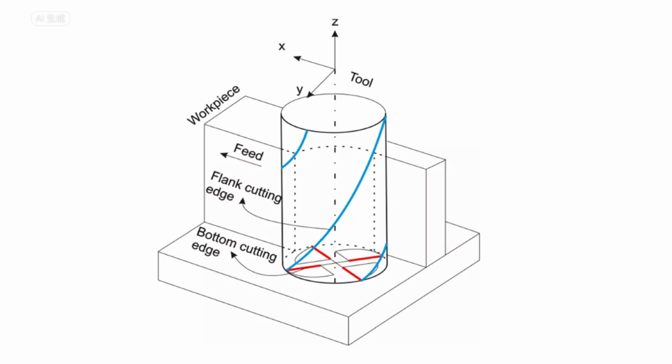Milling process. Once the program is running, the spindle rotates the end mill tool, and then the cutting edges interact with the material and form the chips via shearing. Edges at the end perform axial cutting and side edges perform radial cutting, whereas the helical flute design facilitates easy chip removal. The entering angle and cutting path depend on the CNC program. The same program codes dictate the spindle to move the cutter across the XYZ axes.